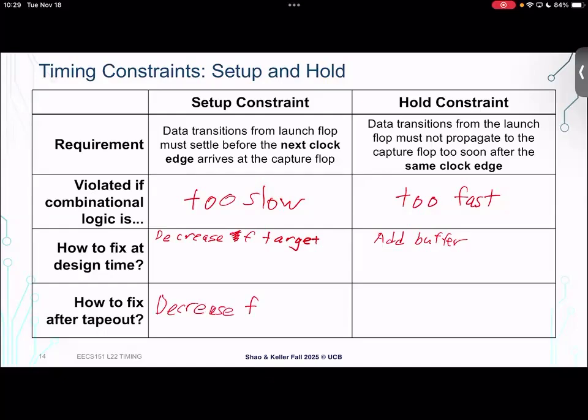Right? Not so secret is that production silicon that is in your phones and computers is doing this all the time. Companies will sign off at a very aggressive target, 3.2 gigahertz or something, and then they'll ship at 3 gigahertz because it didn't quite work. It sucks, but you can still get the chip out the door. There are of course other ways.